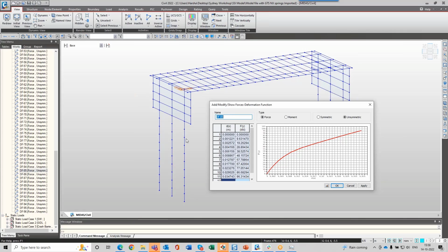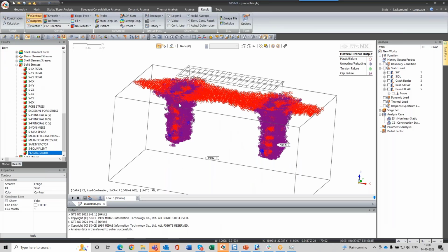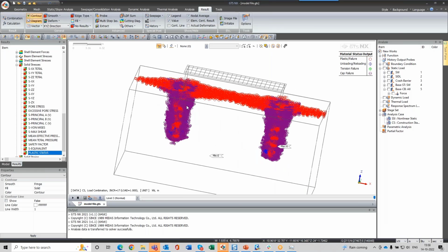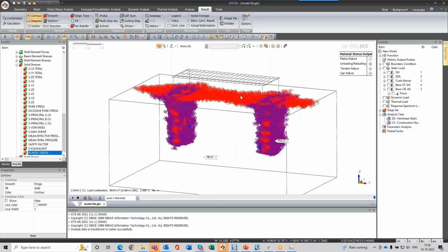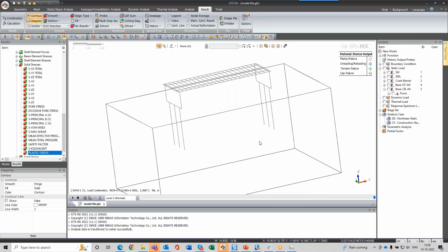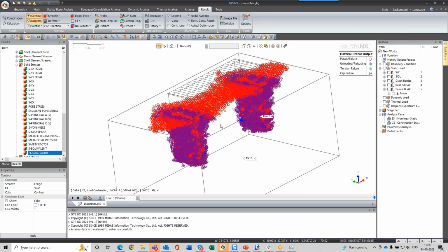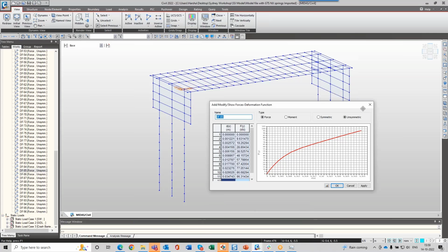So the region itself is different, right? Because in this software, when you see the plastic status, in some cases there is unloading behavior, unloading failure, reloading, and in some cases we have tension failure. And this red portion is a plastic failure. So that means the plastic failure is not uniformly distributed throughout the model. From top to bottom, you might have different springs.